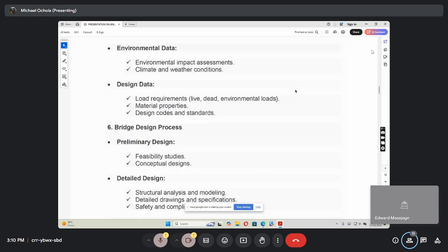You can actually start with concept notes and conceptual design, whereby, as I've told you, you need to know the span range and span-deck ratios, the typical deck section, which is guided by the load, geometry and the rest of it. So in this preliminary design, you can do more from the first visit. You should be able to come up with something like concepts. Then feasibility requires some data collection, and different people have to come in.